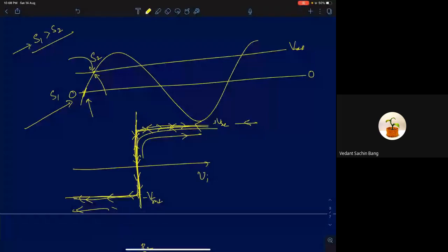One way to fix this, theoretically, is that, let's say you increase your input, and at this point your output has changed. So the output has become plus VSAT. Now, after the transition has taken place, you don't want to trace the same path back, because if you do that, your output will become minus VSAT. Instead, you suddenly change the threshold point itself. After the transition has taken place, you change the threshold point itself. If you do that, then the output will stay where it is.